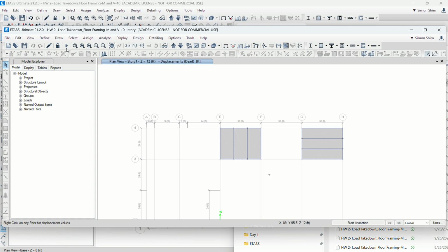Okay, can you calculate the shear? 2.14 times 24 divided by 2, so 24 feet divided by 2 is 12. So 2.14 times 12 is 25.68 kips. Something like that.